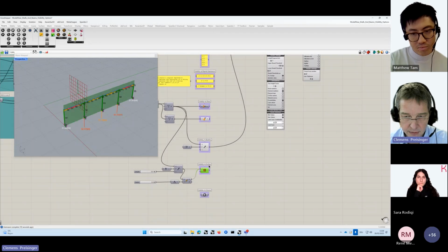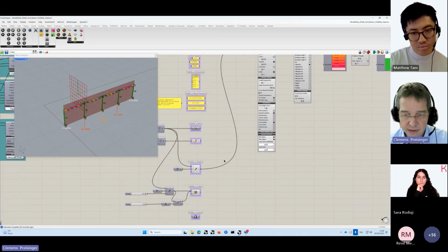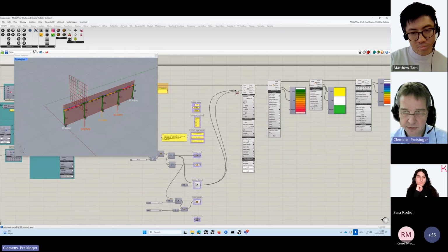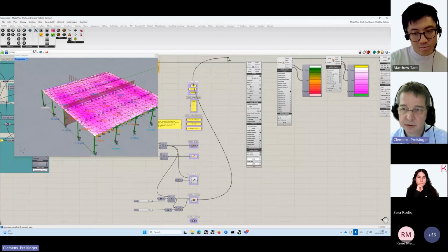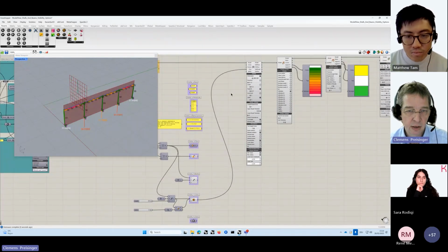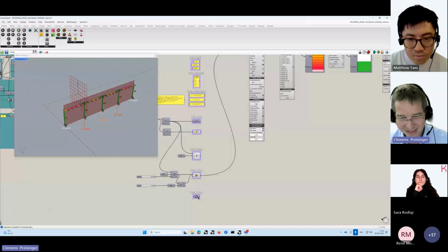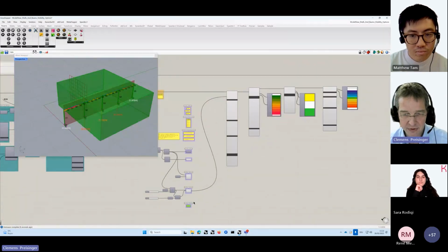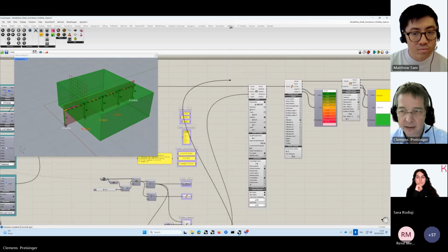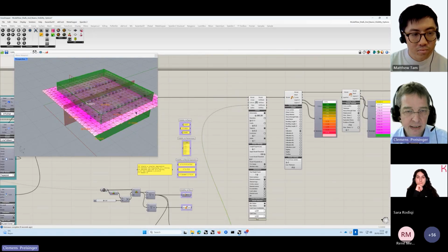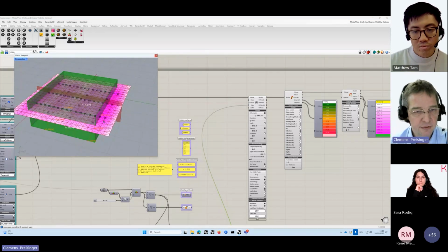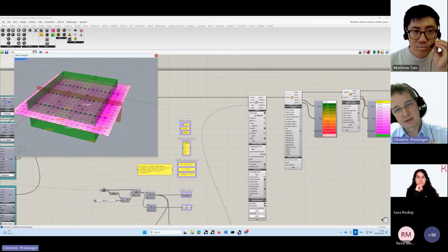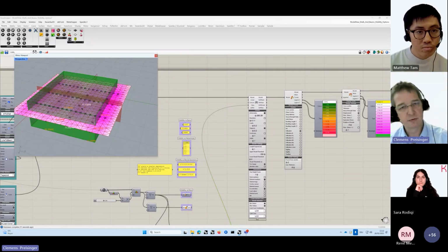And nearly the last option is to specify the view via a surface. In that case, only those elements which are in the surface are visible. Or the last option is to have a closed volume, an arbitrary one, and then you see all the elements which are inside the volume. As you can see here, the roof is also visible because there are some points which are inside. So it's actually only necessary that some nodes of an element are inside the volume to make it visible.